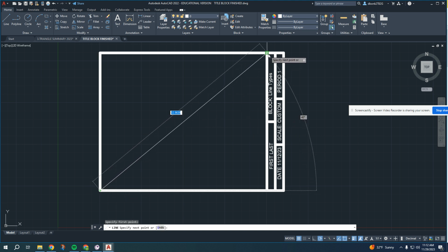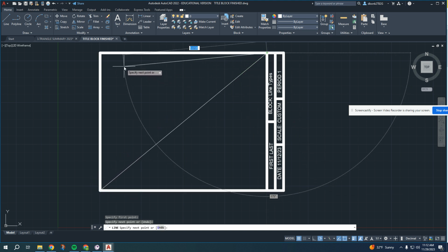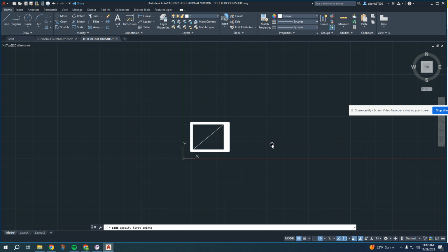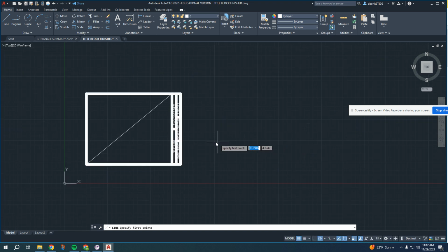And drawing a diagonal line through or an X through any shape, circle, rectangle, square, finds the center of it. In this case, the center is picked up by the midpoint tracking. There's a triangle that if you go over that with another tool, it's going to say this is the middle. I'm going to draw a box and grab the middle of the box and then put it over the midpoint of this line. And that's how we're going to center things up.